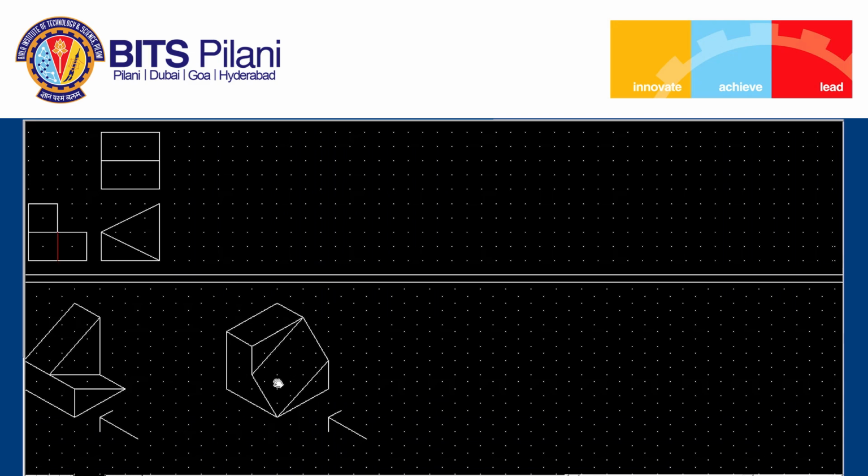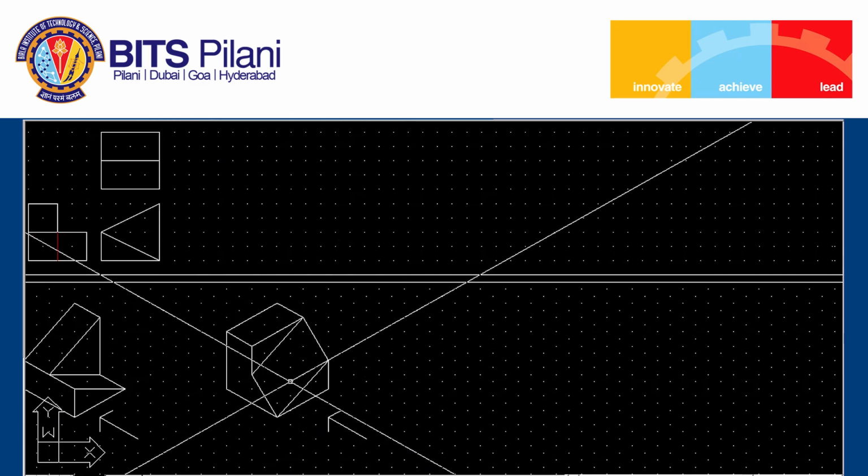The given surface is a skew surface, because none of the edges of this surface is along the principal lines. So while locating the skew surface, we will locate the corners of the surface and then join those corners. So, let us first find out the dimensions of the front view, top view and side view.